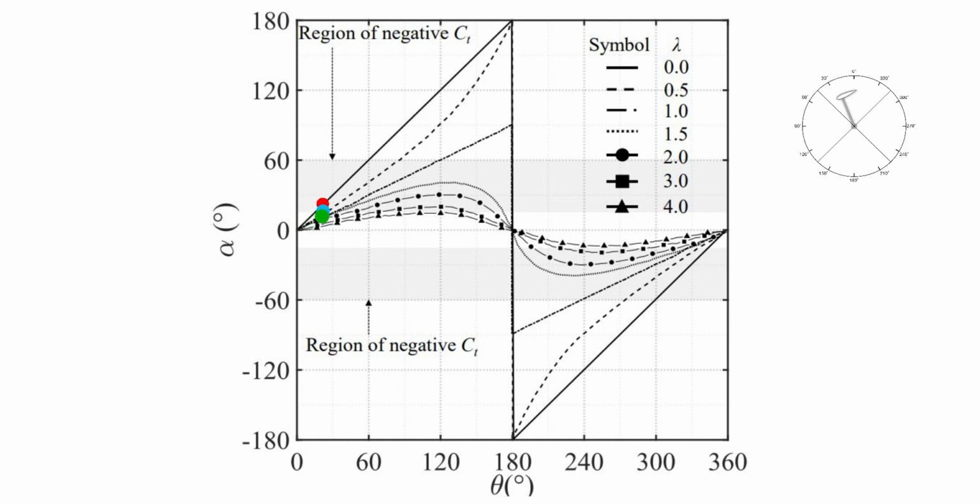For the tip speed ratios of about between 0 and 1.5, you can clearly observe that as the blade starts at 0 and rotates about the axis, the angle of attack extends beyond plus minus 60 degrees, really high. But notice that as the tip speed ratio increases, the angle of attack range decreases. By the time we hit a tip speed ratio of about 4, the angle of attack ranges from about 0 to plus minus 10.